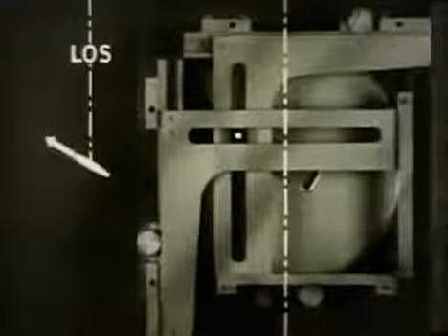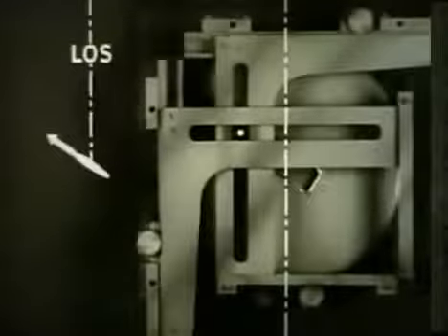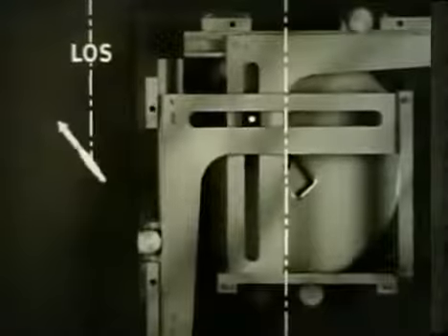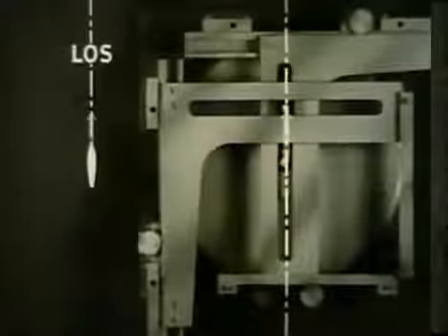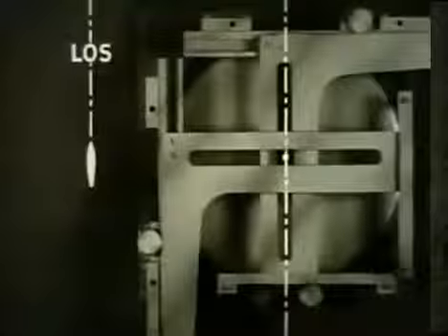When own-ship's course is along the line of sight, the bearing rate component becomes 0. And the range rate component is equal to the speed vector. At 0 speed, both racks cross at the center, and the outputs are 0.